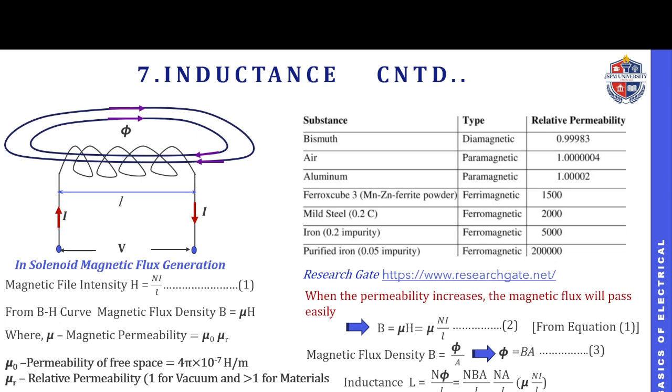So from this we can conclude that inductance varies with respect to the number of turns, the area of the conductor, and the length of the conductor. With this we understand the importance of inductance and how one can derive the inductance value. There are two types of inductance, mutual inductance and self-inductance. Wherever required, I will explain those things. Now you can study what is meant by inductance. Inductance is nothing but L is equal to mu into N square A by L.